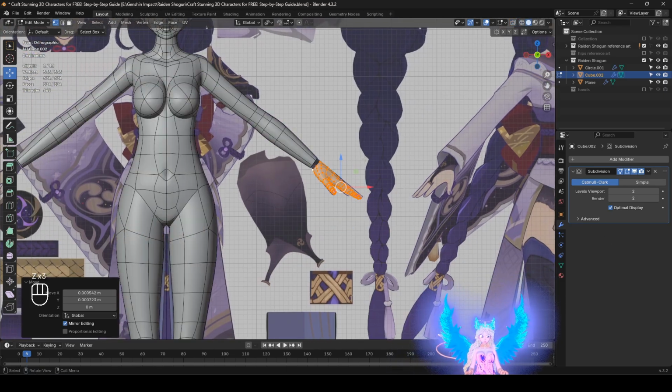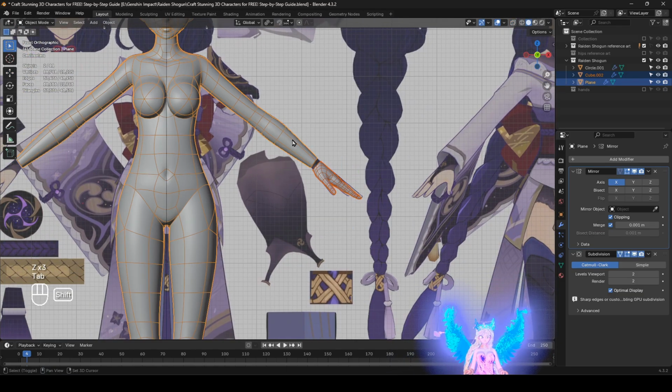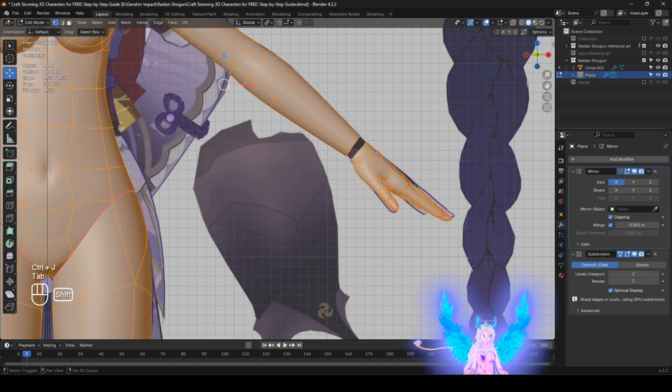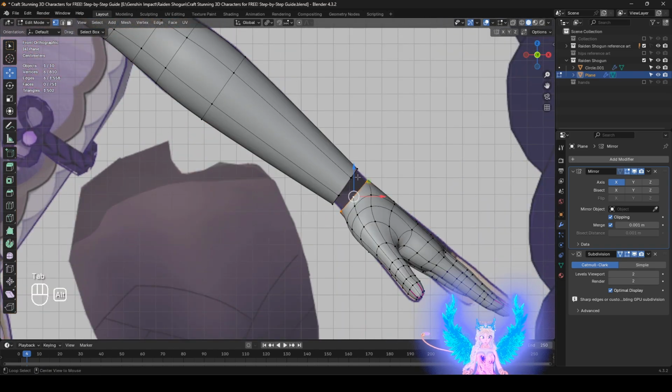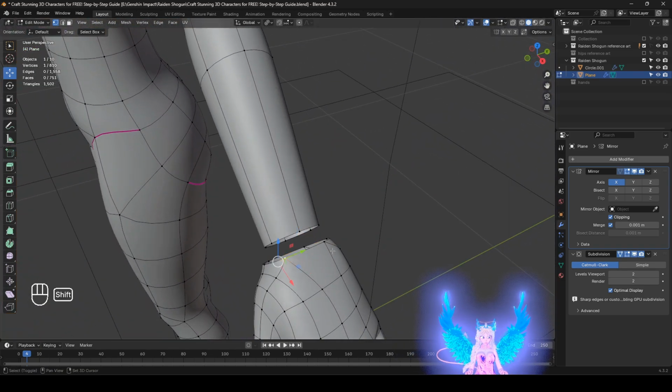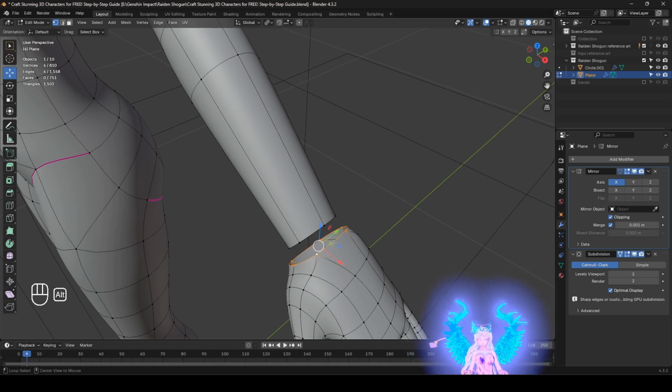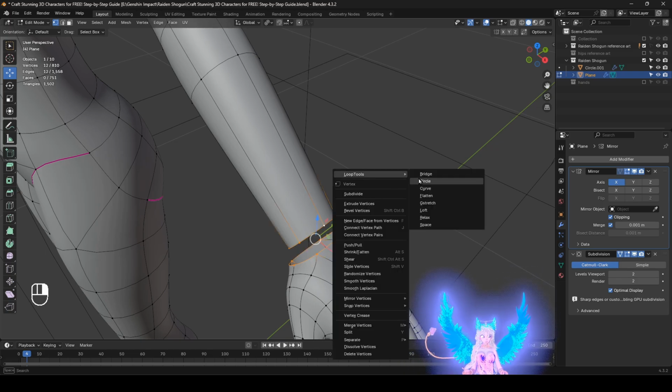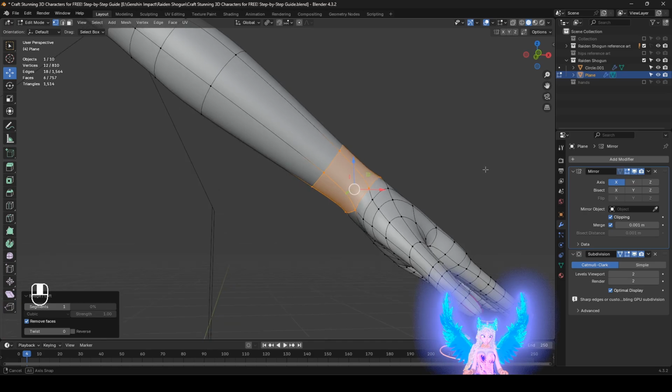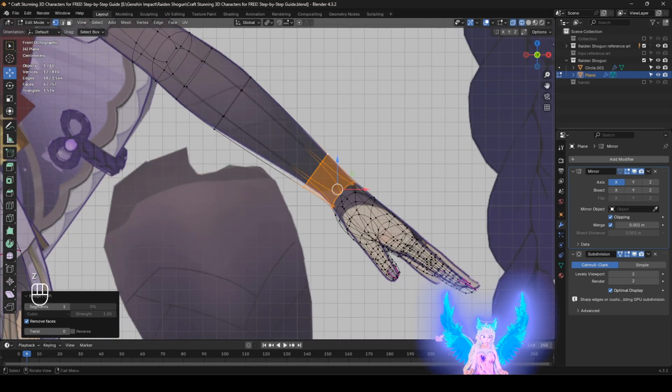All right. Make sure you go in edit mode. Hold down Shift. Click right here. Right click. No, I'm sorry. Control J. You just fused it together. After that, then go to here. Alt left click right here. Well, this just depends. Let's click right here. Hold down Shift. Here. Right click, Bridge, or you could do it manually. It is up to you. It doesn't matter too much.